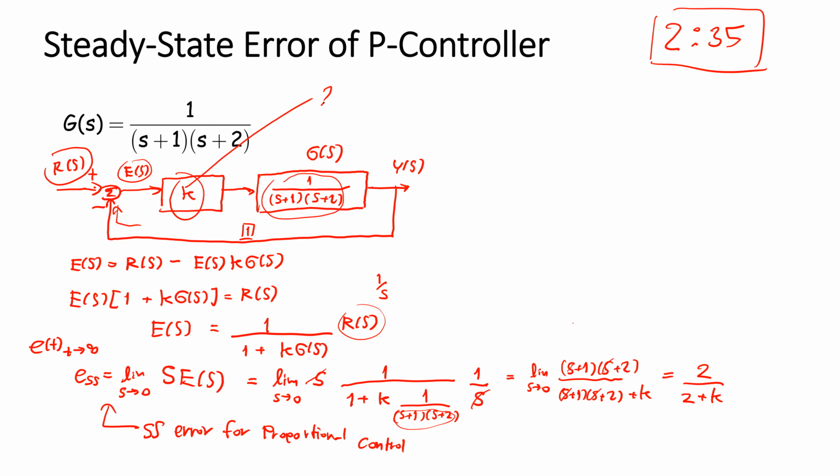To achieve the desired damping ratio, we need to use the root locus to find the gain K so that the system still has the damping ratio 0.7. With proportional gain, the open loop transfer function is directly this one because the controller is just proportional.